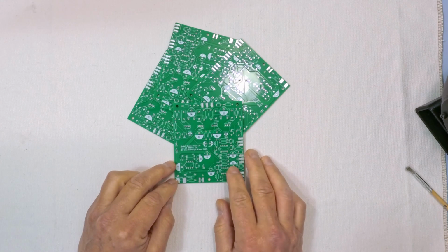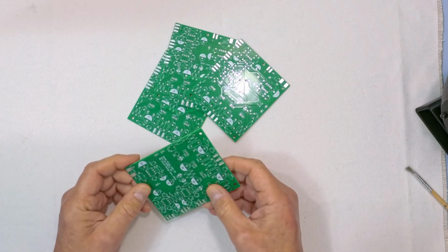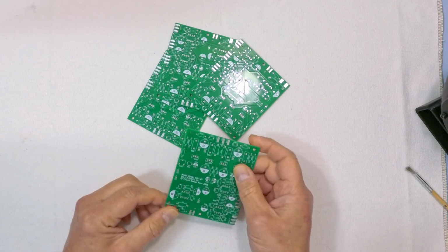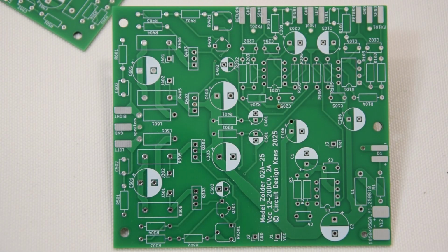To get the best sound quality out of a PCB, there are a few design principles one can keep in mind. Maybe we should talk about that a little bit. First, it's recommended to isolate low-level input signals as much as possible from other signals and power traces. They are the most vulnerable to interference from other signals or power lines. Not only do you have to isolate, but also keep the traces short to minimize the risk of picking up noise.